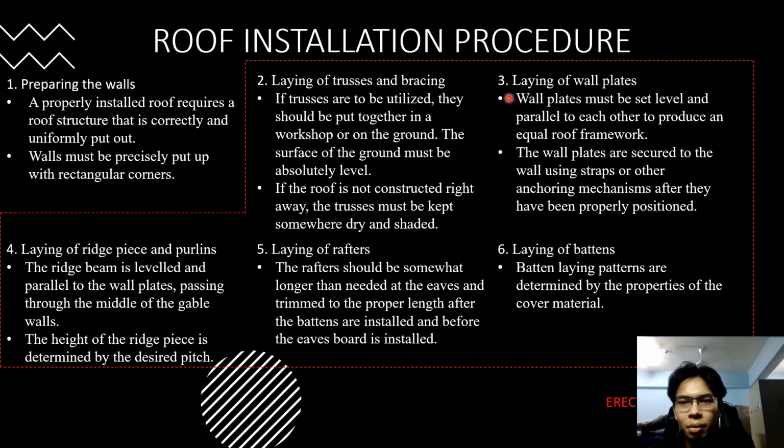The third step, laying of the wall plates. Wall plates must be set level and parallel to each other to produce an equal roof framework. The wall plates are secured to the wall using straps or other anchoring mechanisms after they have been properly positioned.